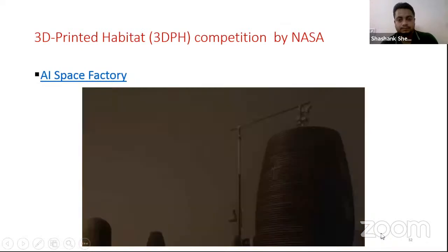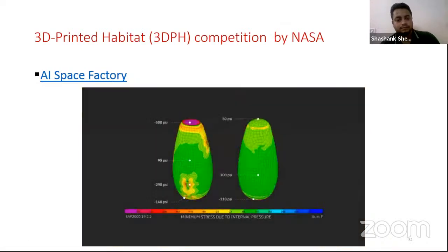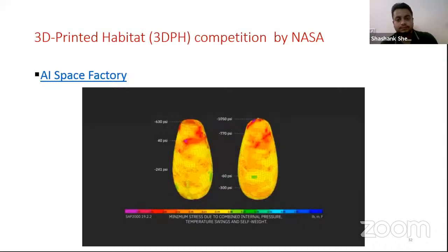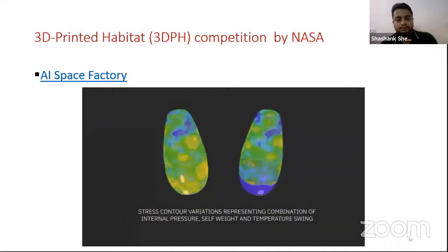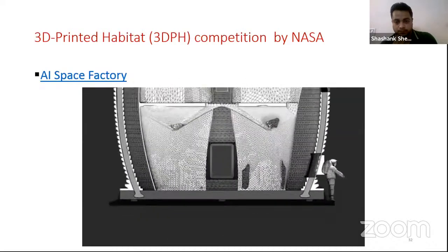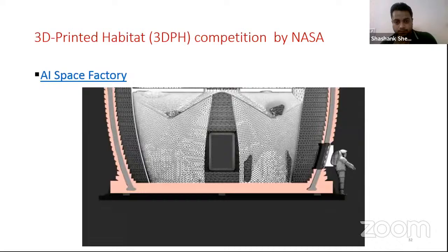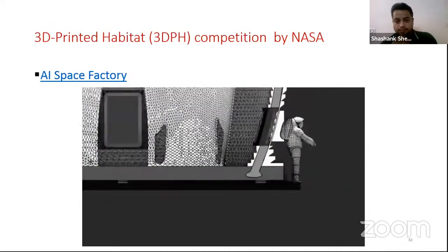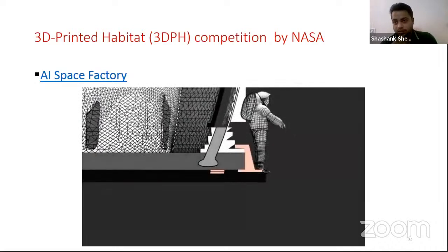Apart from pressurization, Mars's drastic thermal swings mean that any structure not allowed to expand and contract will fail. Our solution to this is twofold. At the ground, we render the shell and its base as a single structure, a flanged shell that moves on sliding bearings at its contact with the ground. This is the base isolation concept, while soil anchors are also used to secure the flange against uplift.